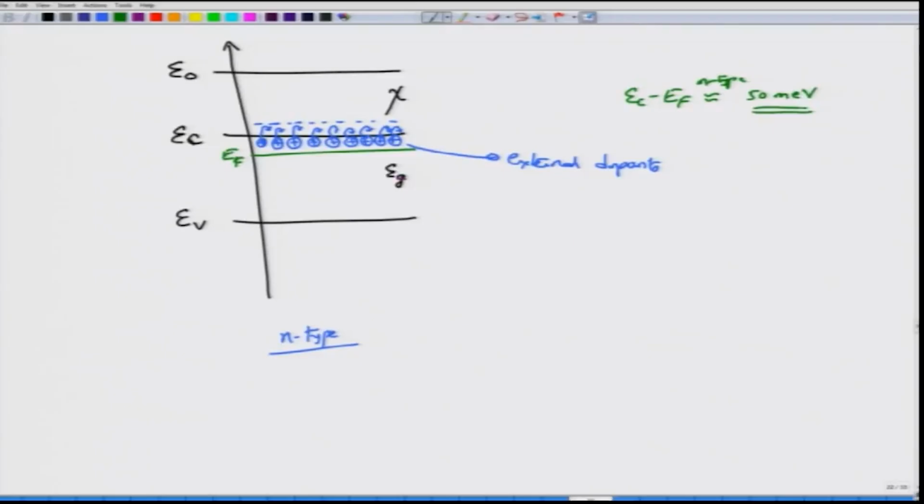So, it is actually quite a small gap between the Fermi levels, and then I will put an N as another subscript so that we are dealing with n-type materials. If you look at the concentration of the electrons, there is a huge concentration of the electrons which of course falls off again over the range of some 2 kT, and because you are now operating at a level above 0 degree Kelvin, there will be a few holes as well.